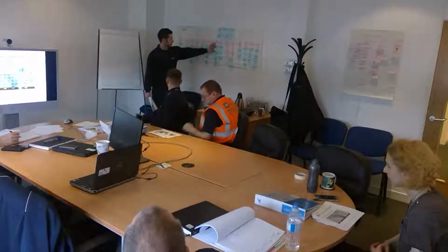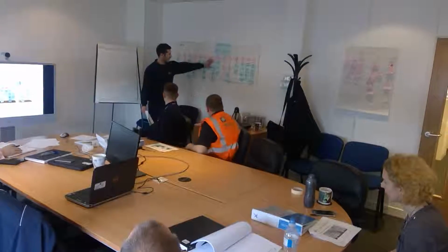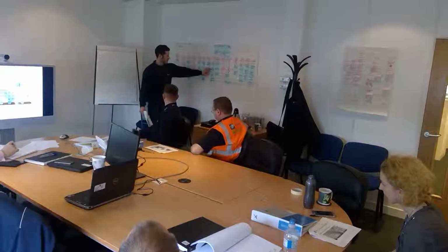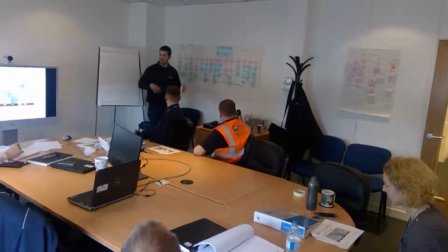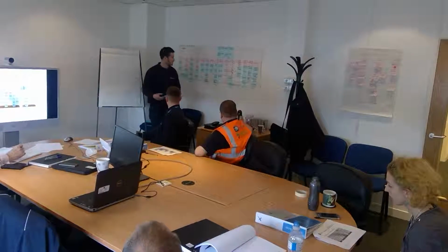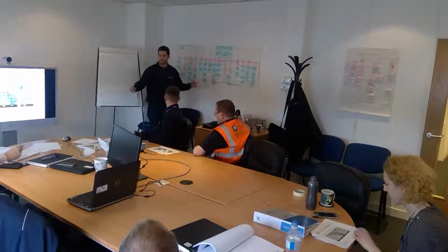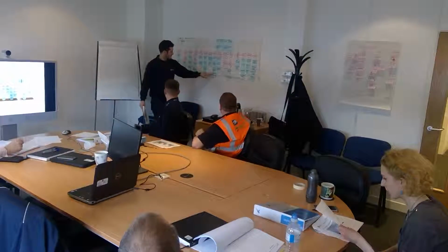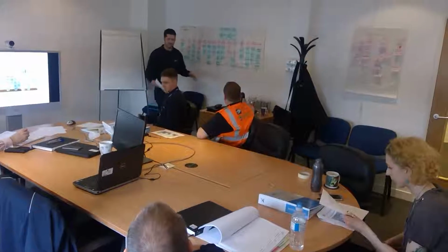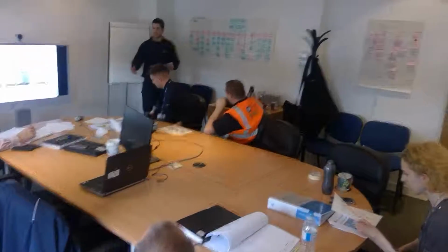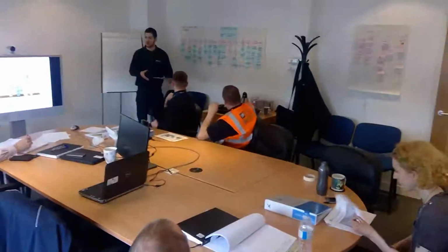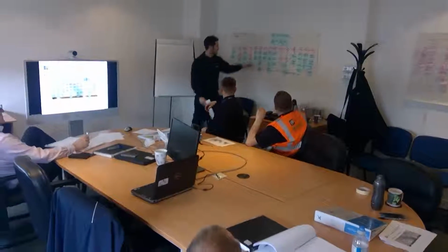We're then on to welder, so welder then comes in. He'll set up and tack the pipe, he could tack it up wrong. Cross-contamination, if you haven't decontaminated his bay from stainless steel to carbon steel, we have a process to follow for doing that. Crane can break down if it's a large item, we can't then get it in shop. And waiting for assistance, so the welder might be waiting for another fitter or a team leader to come and hold him an elbow on or set him a bend up, something like that.